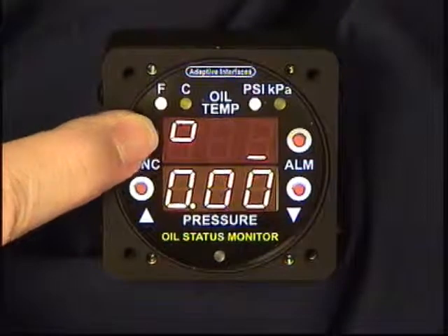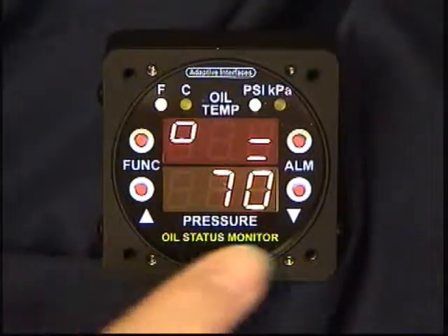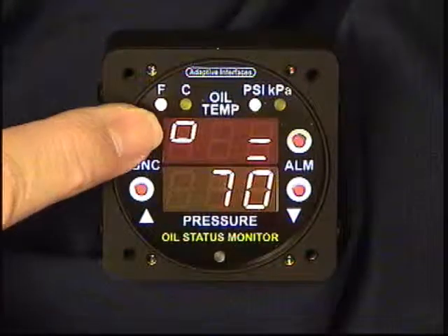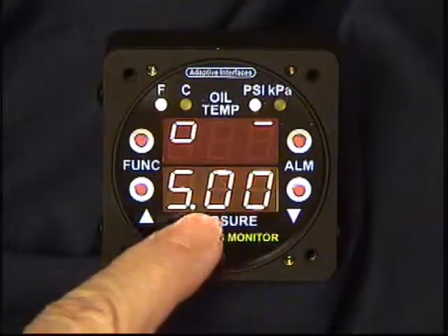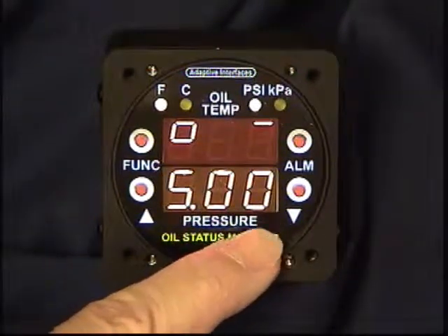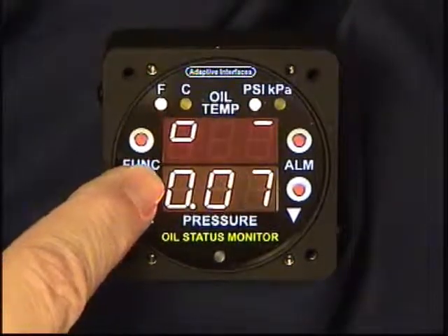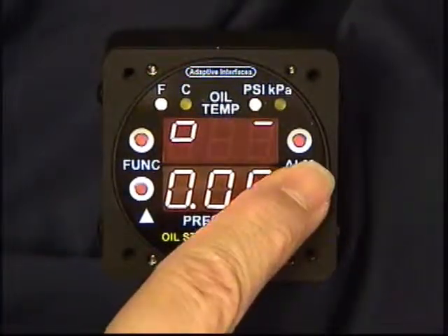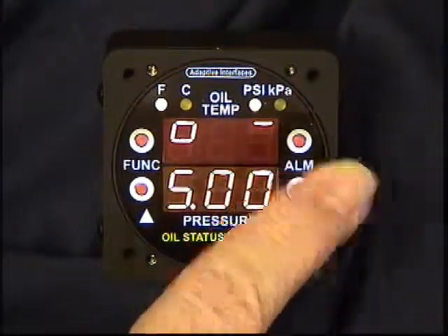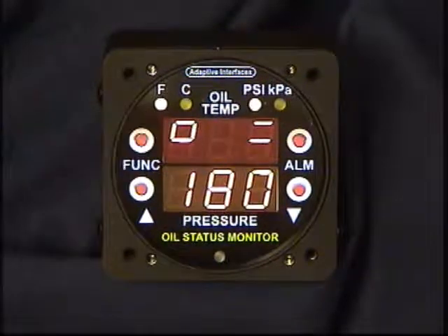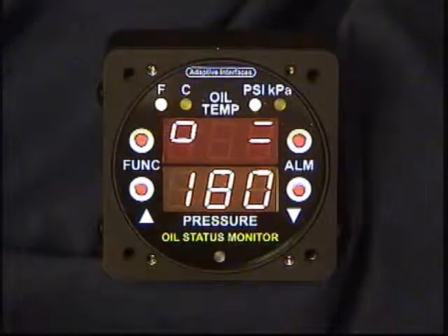The second value is again the actual temperature associated with that data point. Next function is a value of the sensor. Right now the default is set for 5 volts. It can be lowered or actually brought up past 0 to whatever value you want. And you can associate a temperature with that as well. Next function is the associated temperature, which is 180.